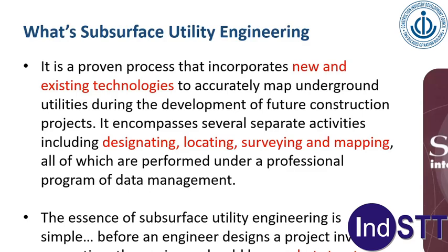Before an engineer designs a project involving excavation, the engineer should know what structures and conditions are beneath the earth and where they are in 3 dimensions. Such structures are usually utilities but may include underground storage tanks, septic fields and other things. That is basically what SUE is. It is use of new and existing technologies to accurately map underground infrastructure before you design a construction project or you execute a construction project.